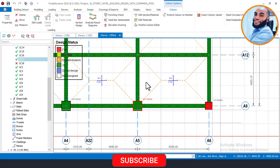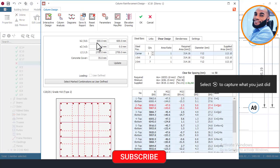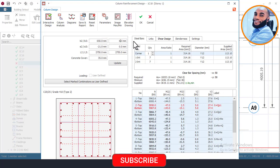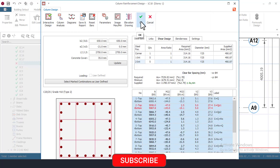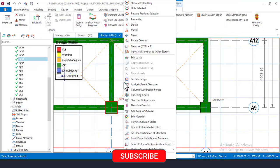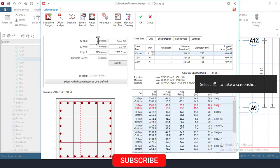And I'll come again right now on this side again, it's also the pool side. Click on this place here, then say properties here, okay, sorry, design here. This is the pool side. Let me try 650 there and see what kind of bars I'm going to have. 650 also, and then update here, reset bars and design. Okay, let me see what I'm going to have. Yeah, that's okay. So I can just come right now and say okay, and then okay. And then let me see if this can pass with diameter 25 at 650. Let me see that again, 650 and then 650.